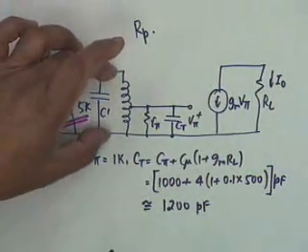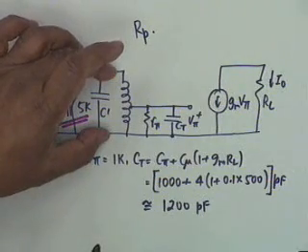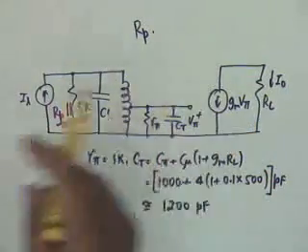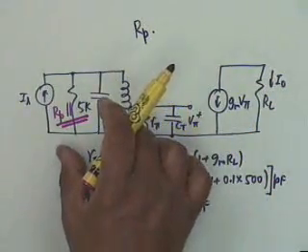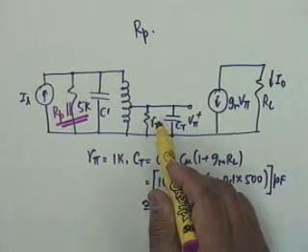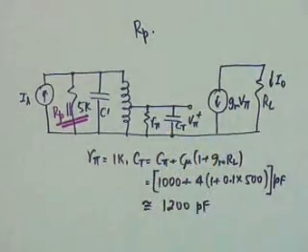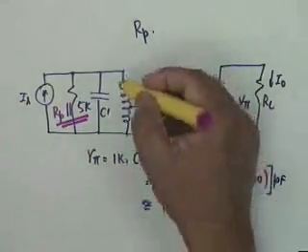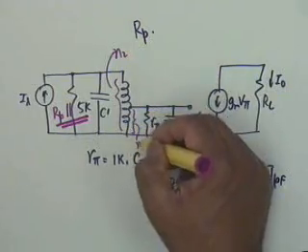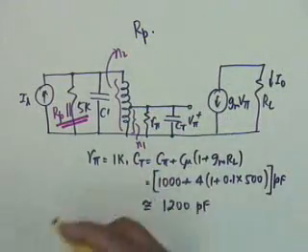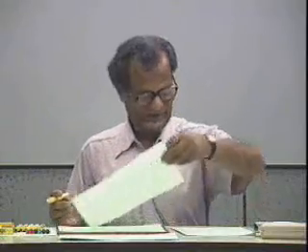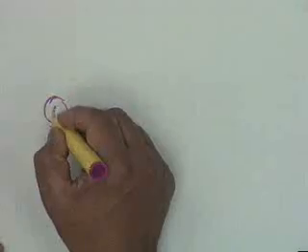No, because it is across the total, and therefore the total inductance has to be used. It is R pi and CT which will be reflected into the input circuit. R pi would come as R pi multiplied by, that's right, that is R, no, that's wrong. This is N2. This is why I said I will bring variety into experience. Okay, R pi by S square, and CT would come as S square times CT. Okay. So, let us look at the input circuit now.